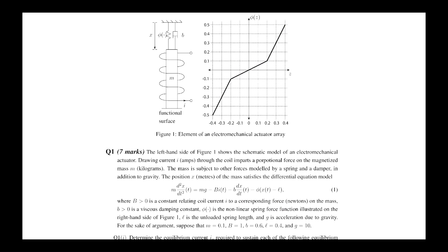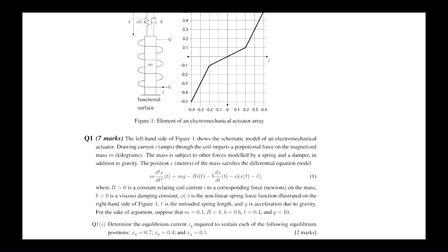So you work in the time domain to do the linearization in the way that we've seen many times. Then you might have to take the incremental model into the frequency domain to say something about where the poles and zeros are. Is it stable? Is it not stable? What might the step response look like? That sort of thing. It's fairly standard stuff, with models that are given to you.